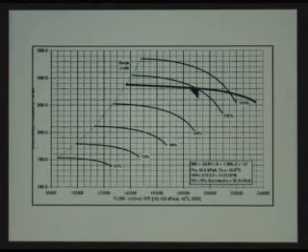But what happens, and this goes back to when we were doing performance considerations, this is the curve that we were told we were going to have. This is the curve that it actually ended up on the test stand. So now we need to evaluate, is this an acceptable curve for us to operate on or not? Obviously, on the old curve shape, we had a very high pressure rise to surge, which gave us lots of controllability by that valve.